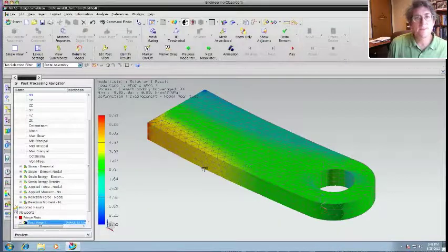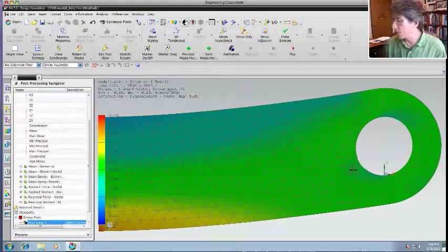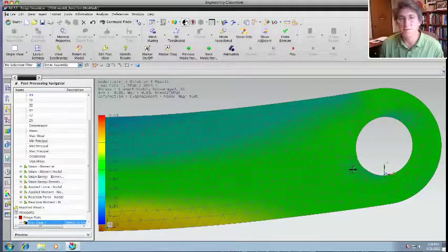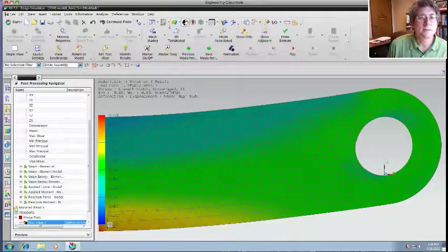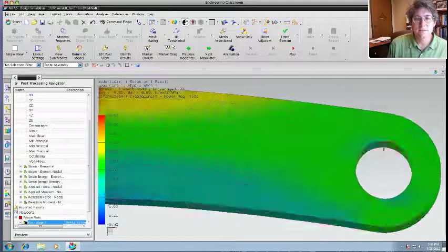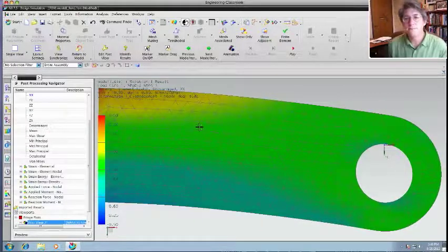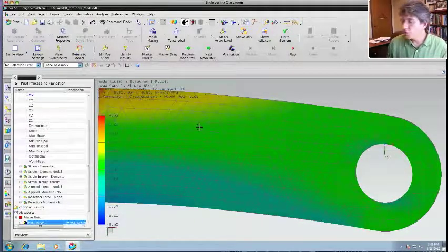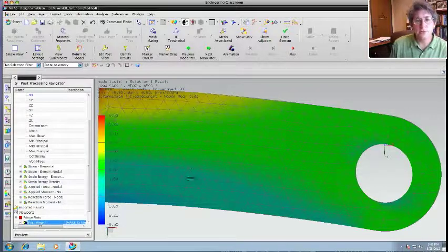And if you look at this, let's look at the side, the top view. Actually I had the load going up, so this gets flipped. There you go. Okay. If you look at this, you can see the distribution if you follow my mouse. On the top side, we have positive stresses, and on the bottom side, we have negative stresses. They're compressive. And through the middle, it about goes through zero.